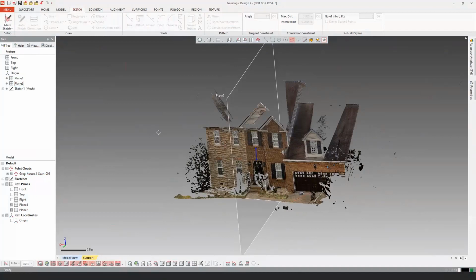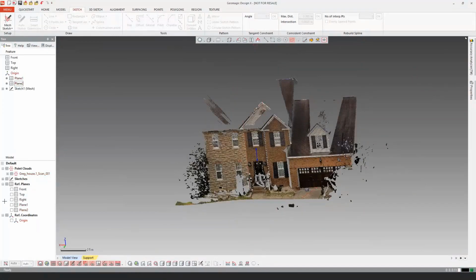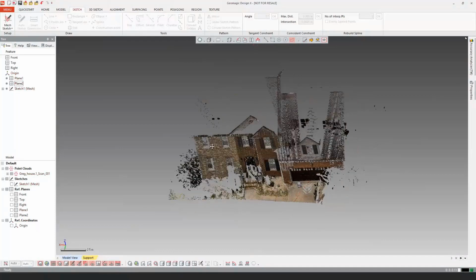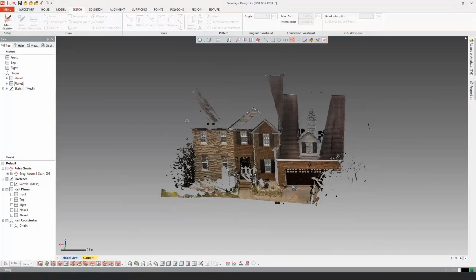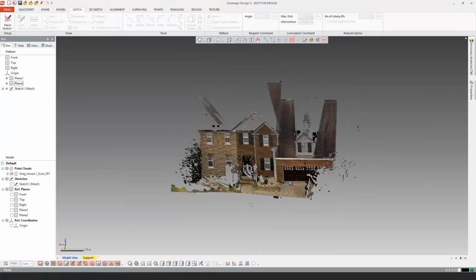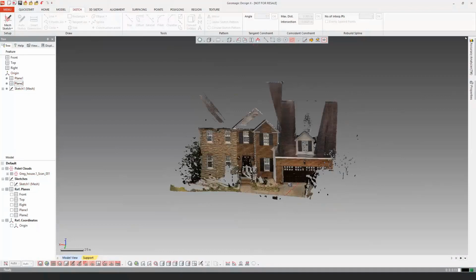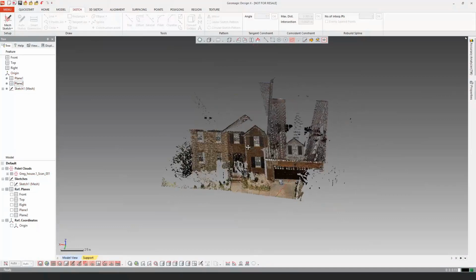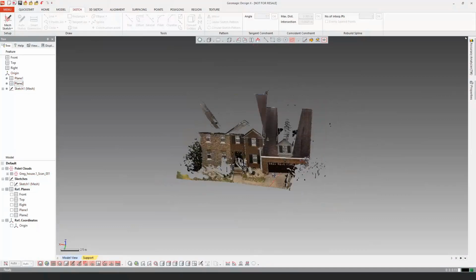So, talking a little bit about going into submeshing as we go along here, what I'll do is hide these planes, and I'm also going to hide my reference sketch out here. And we can talk about some different meshing methods. Oftentimes, you will not mesh a whole model altogether. Now, if I brought in scan data from wrapping all the way around this house, I would usually mesh this in sections. I would usually do each scan individually, and I may or may not combine them,